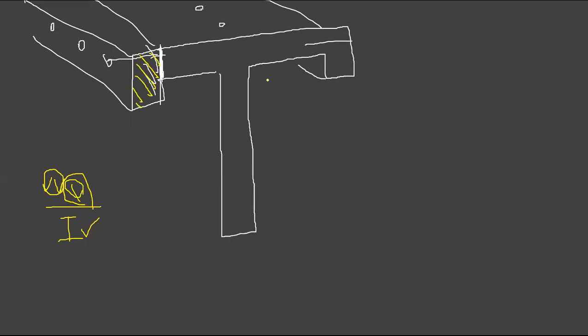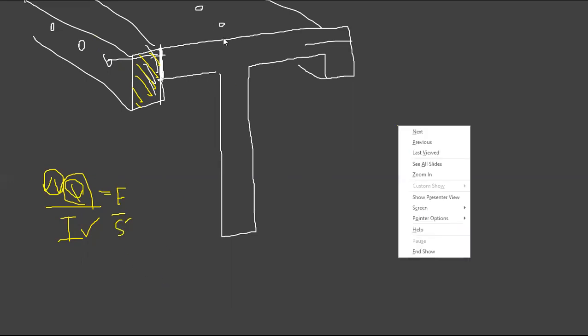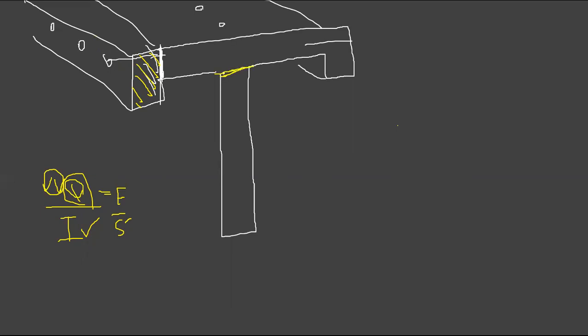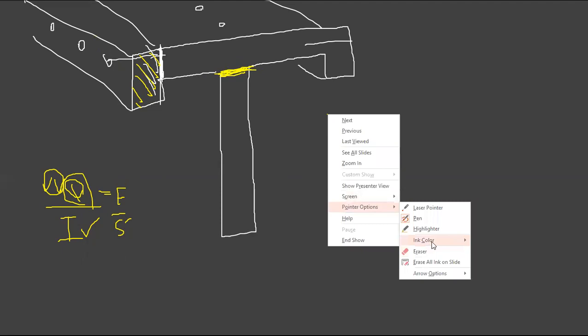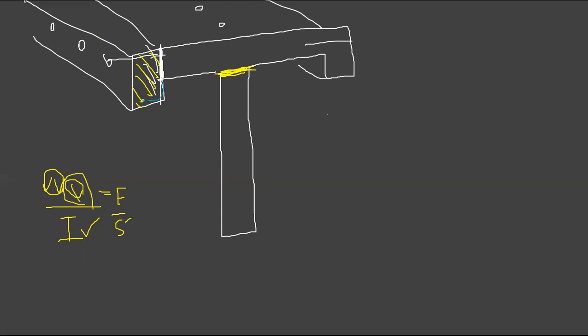If you need to find this value, it is going to be these nails divided by that spacing, let's say it's dash. For these nails, that will fail at this connection, because this built up member is connected from this. For that, you need the first moment of area of this entire portion.